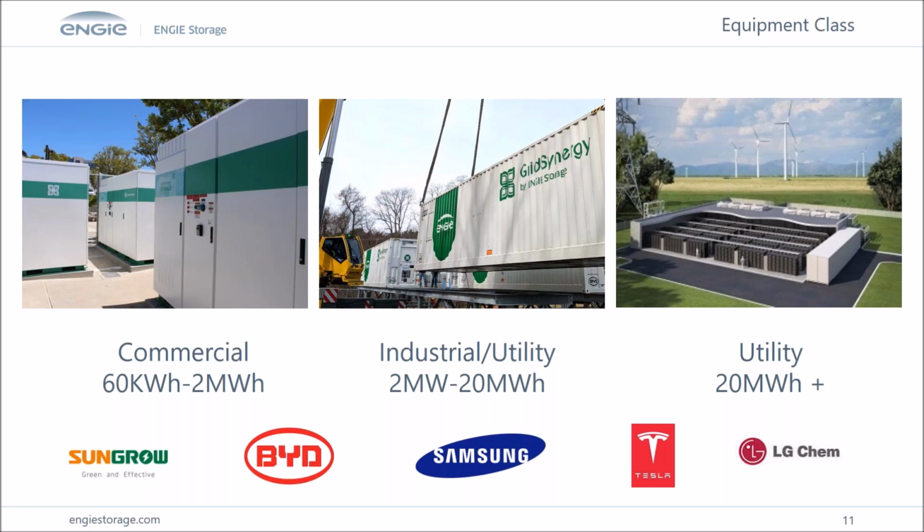But when you combine with solar, that may go to 3 hours or 4 hours of batteries in order to get longer duration, or for building loads that tend to be flatter. On the commercial side, the most common building blocks that we see are a 30 kilowatt, 40 kilowatt inverter up to about 1 megawatt, maybe sometimes even a 2 megawatt inverter, with the batteries being slightly bigger. Those tend to be modular systems that can be used as building blocks.